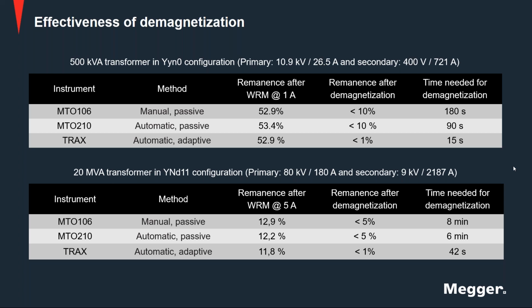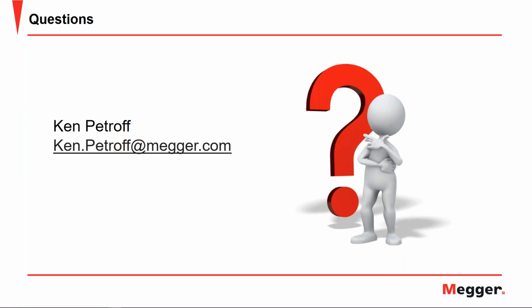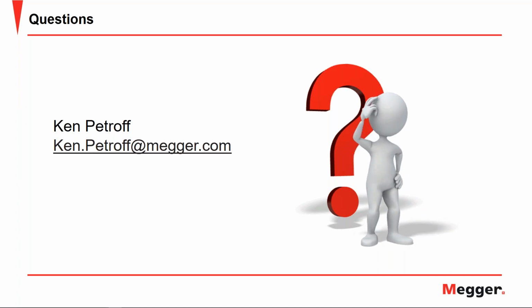And as such, once we demagnetized it, it was the only way we could get the excitation currents back to within expected levels. So yes, it does stay magnetized. And does it eventually demagnetize itself? Not by any method that I am aware of.